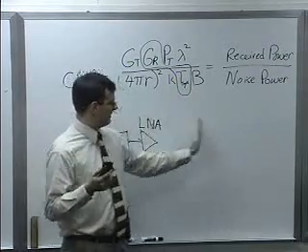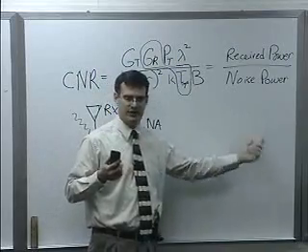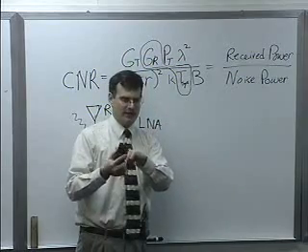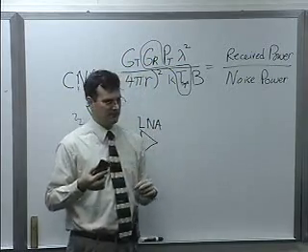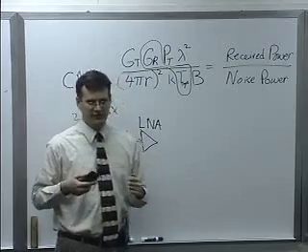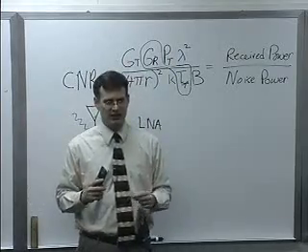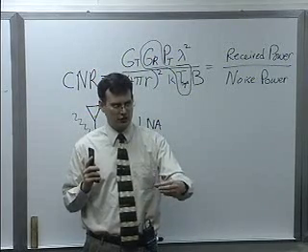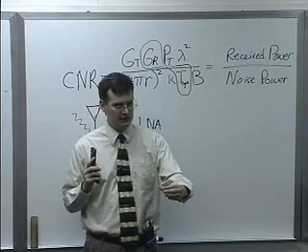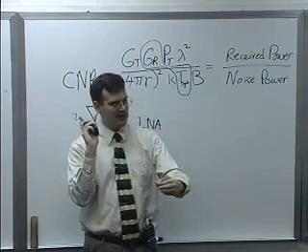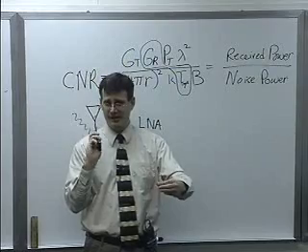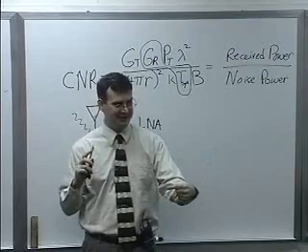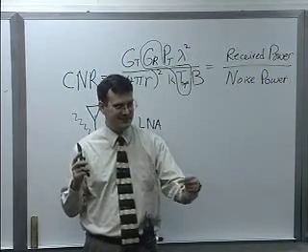Let me say, later on down the line, we're going to put a nice bandpass filter here, on the RF chain of my Wi-Fi card, that should knock out whatever signal comes out of the phone, because they're about 60 megahertz apart, roughly. So okay, everything's going to be fine, right? But wait a second. Remember, this receiver is trying to receive a very, very weak signal. And I've got a signal coming out of the phone, which looks maybe like 23 dBm, 25 dBm, something around that category. And remember, what comes into the receiver is probably like negative 90, negative 80 dBm in some instances.